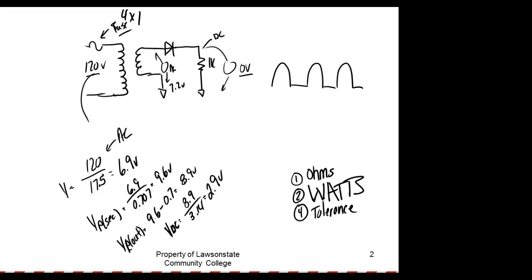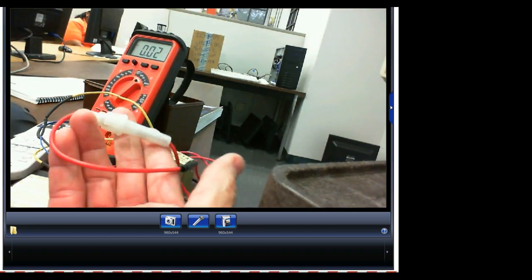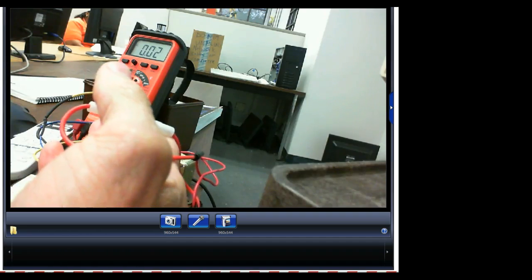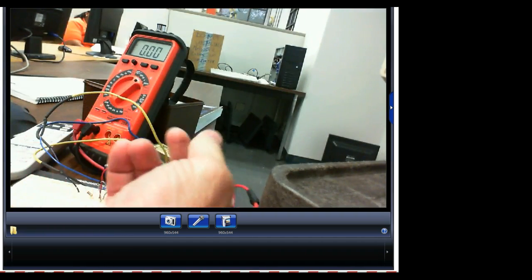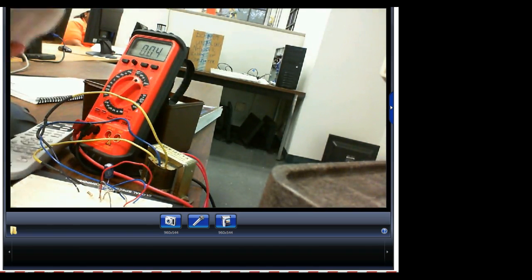Now, of course, if you have a shorted diode in a full wave rectifier, it's going to blow a fuse, if you have a fuse. Your trainer has a fuse in it, and the power supply that I have is fused. I'm sorry, it's in the primary. Running an unfused transformer is not very smart, right? Because in a full wave rectifier,